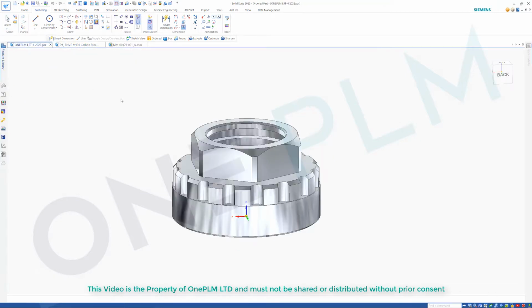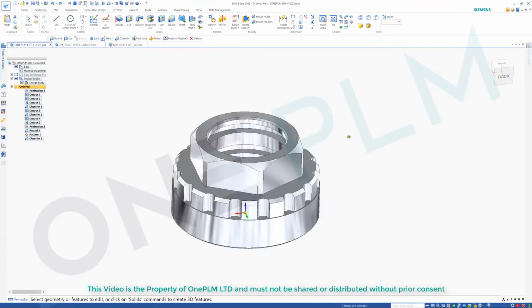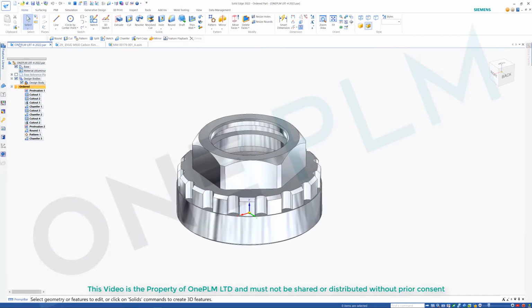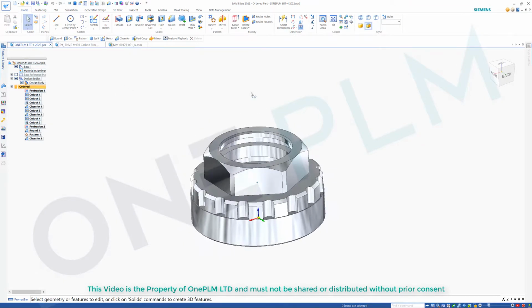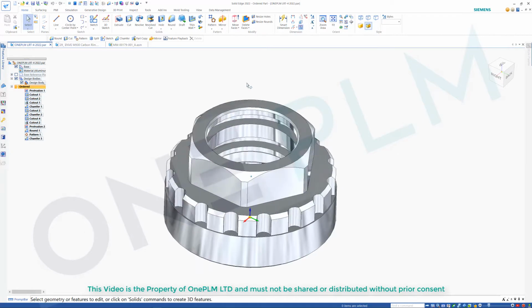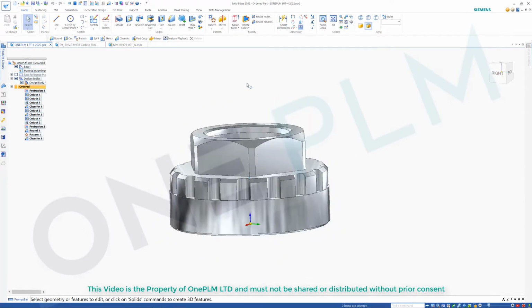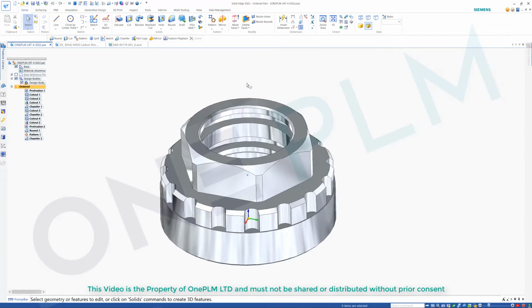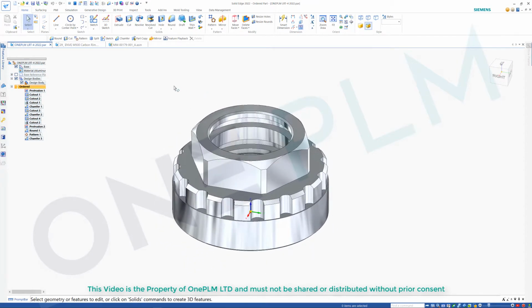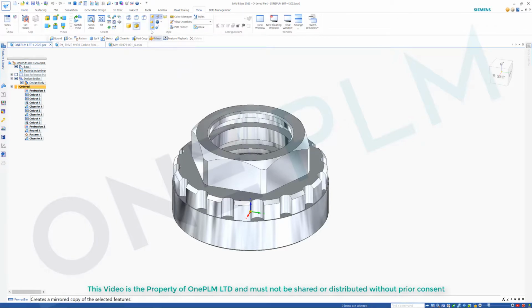So if we open up our little tool part, as I've got it saved, it's 1PLM LRT4. Obviously, I've got it 2022 because I've got it in different versions. So that's just making sure this is the one that's in 2022, so I know it's not backward compatible. Our label tool is in our View tab. If we go to our View tab, and in our Style section, we've got our little decal option that allows us to add a decal label, whatever you want to call it.